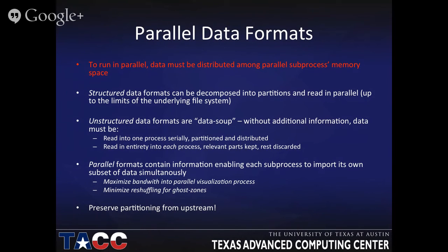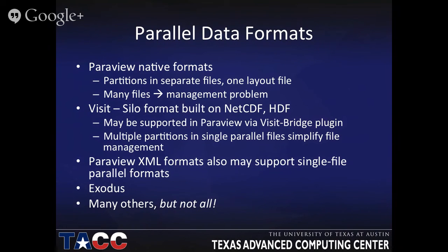I guess this slide pretty much says the same as that last slide. There are a bunch of different native formats in ParaView that do support one file per partition, and that's their drawback. Silo formats, NetCDF and HDF all support multiple partitions in a single file.